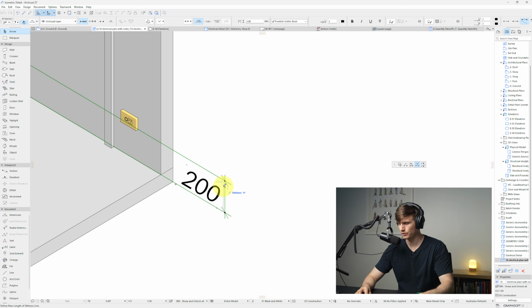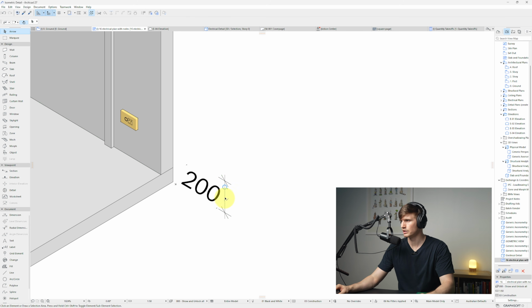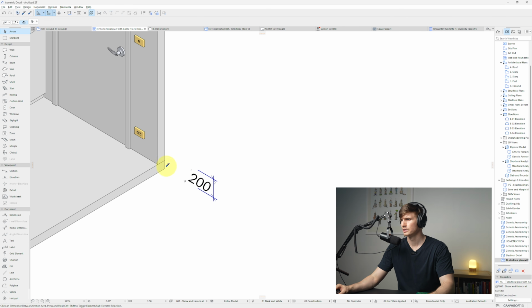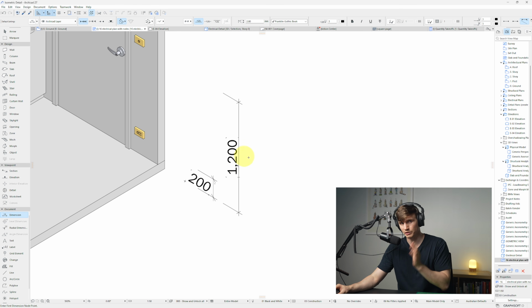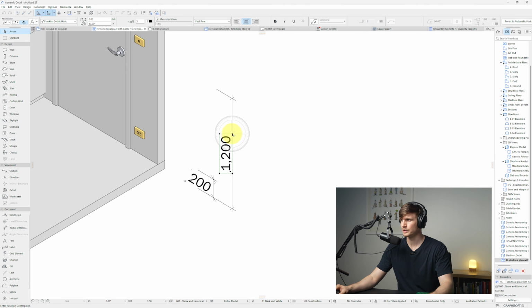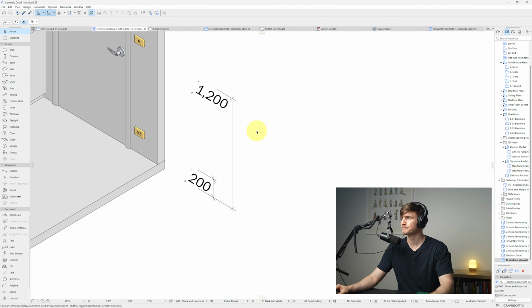So if we say go 1, that's made it quite shorter. If I drag it out, say 10, from here, I'm going to drag this back a little bit further. I can do the same thing with this switch just above. Clicking both points, double click, and then we've got our second dimension. To match in the style, I'm going to rotate this text as well and lift that just up underneath the witness line. From here, I'm going to go to the polyline tool.